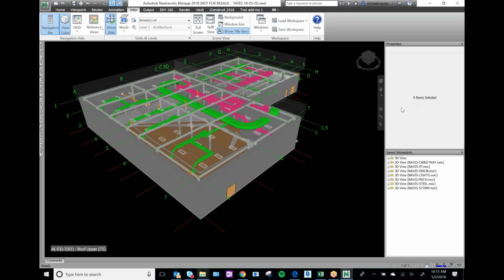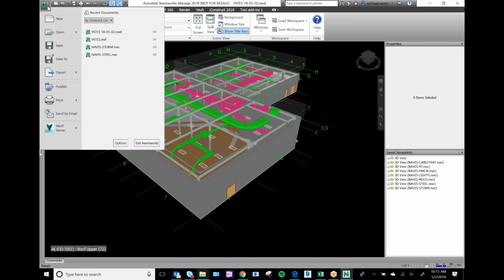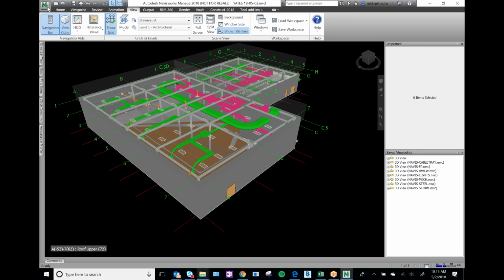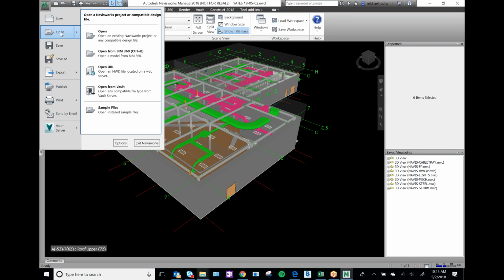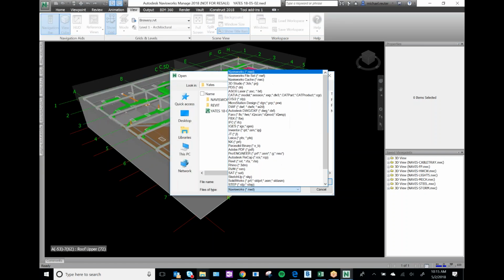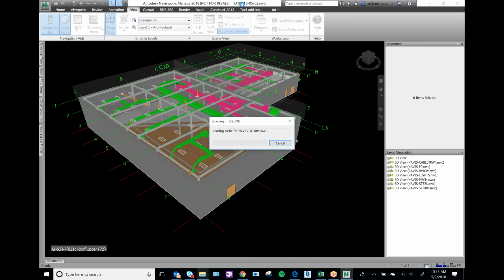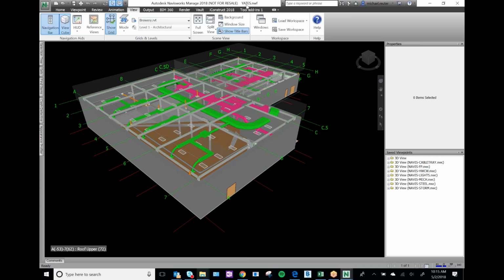All right. So now we've got all that done. Now we're working in our NWD, and we don't want that. So let's hit the Navisworks button, then pick open, and then let's reopen our NWF file. Okay, so we need to make sure that we're working off of just the Yates.nwf file. Okay, everybody following me? Okay, so now I had us set up all these windows.